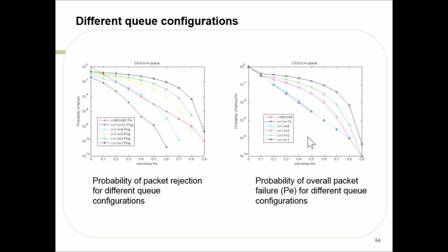And you had numbers that were more than 3-bit soft-decision detection? Oh, you're saying numbers like -5, 13. Okay. Those are soft information, where you could use different numbers of bits. That example is for a 5-bit decoder. That's usually what we use, a 5-bit or 6-bit decoder, for the LLR representation. You say 5-bit decoder, you don't mean 5 bits to represent each bit that you read. No, you need 5 bits to...